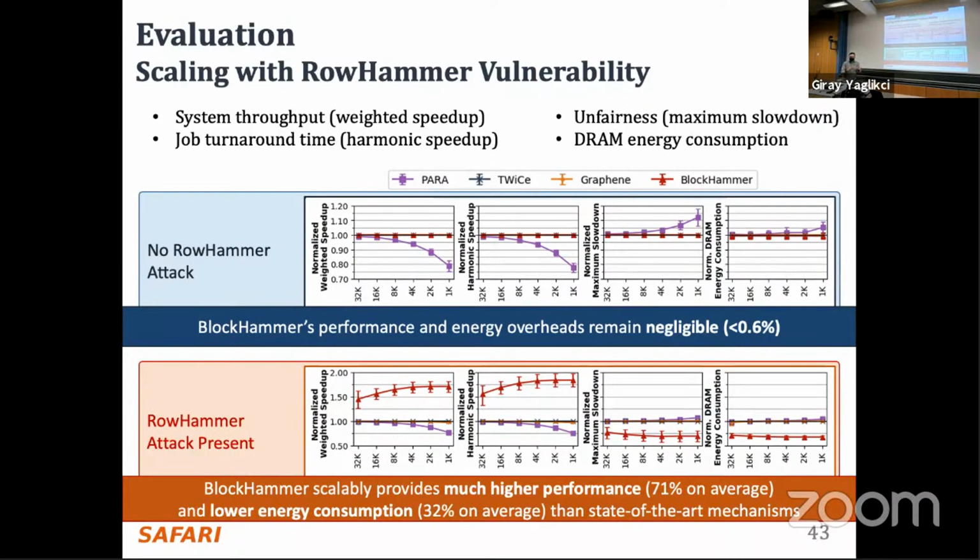It's called interleaving. You can do this interleaving in cache line granularity or several cache line granularities. And we also apply this mechanism called, I guess, minimalistic open page. Based on the row ID, you also change the sorting of these data in different banks. So one row goes from bank 0, then bank 1, then bank 2, for example, and then another row goes bank 2, bank 5, bank 0, something like that.